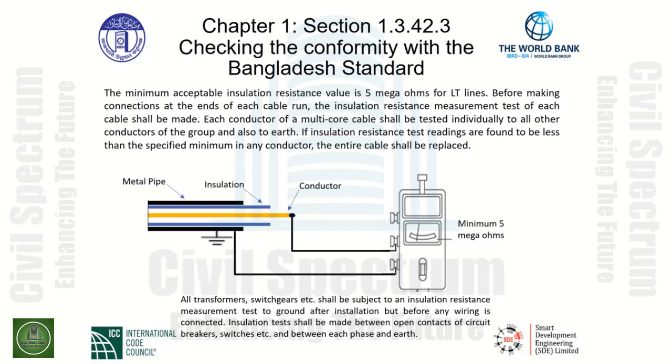be replaced. All transformers, switch gears, etc. shall be subject to an insulation resistance measurement test to ground after installation, but before any wire is connected. Insulation tests shall be made between open contacts of a circuit breaker, switches, etc., and between each phase and earth.